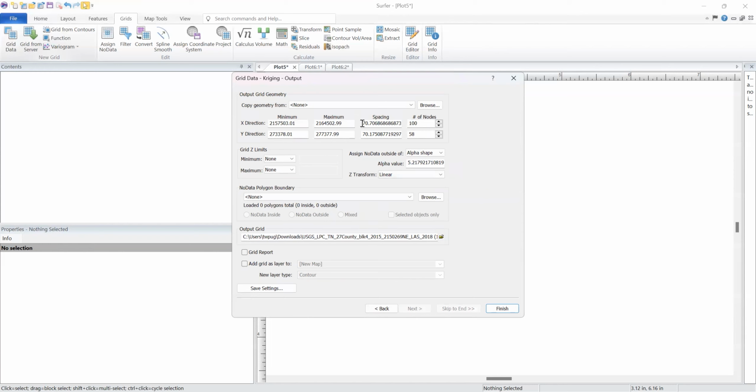Now, what I'm going to do is put the spacing at 1 meter. Now, I'd like to put it at 50 centimeters, but I'm afraid that this data set's so large that it wouldn't successfully process the data. Okay, now you can look over here. We have 7,000 by 4,000. That's the size of the image, which is pretty big, right? And if I put 0.5, both of those numbers would have doubled, right? Okay, so let's just finish it off.